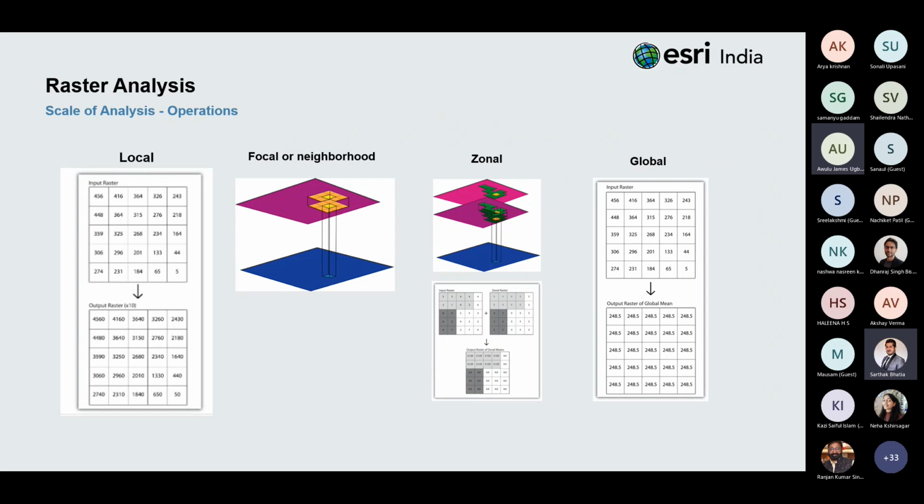For raster data, a zone is actually all cells with the same value. So in case we have a particular set of cells with a similar value, it would formulate a particular zone itself. And a zone in terms of feature data is actually the features with the same attribute values. In case there is a specific attribute value being represented in the raster, if you were to give an example, classification in land use, and we have the land class defined as a particular category of agricultural land or category 4, then accordingly that would formulate a zone.